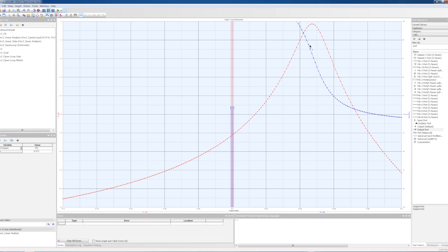And you can see that the phase slope here crosses the 0 mark way down here, which is not at all what we want, because the oscillator, of course, is going to oscillate when the total phase shift through the loop is 0. And if we have a gain of 1 at that 0 phase crossing, then we should oscillate. Now, obviously, we don't have a gain of 1 there. Our gain is going to be, according to this, something like negative 19 dB.